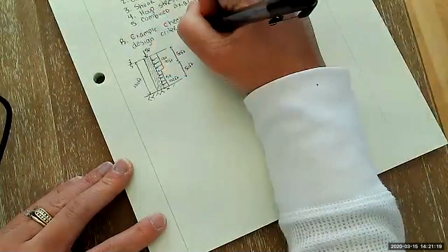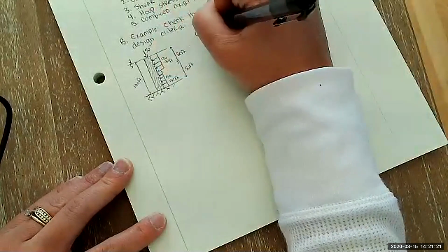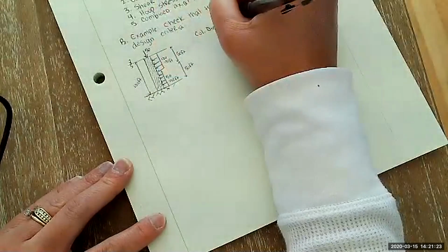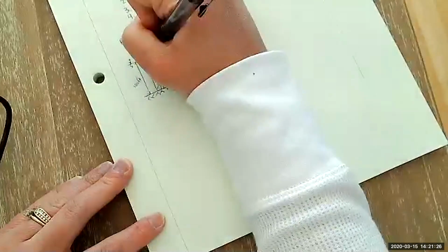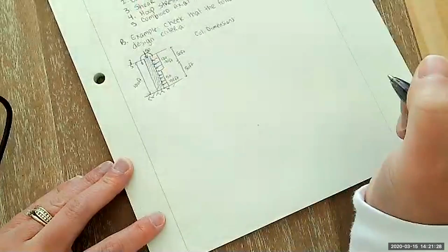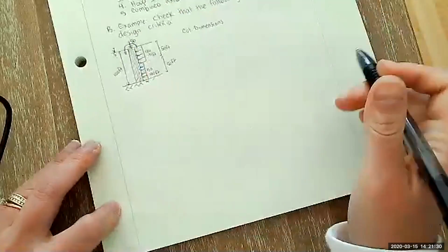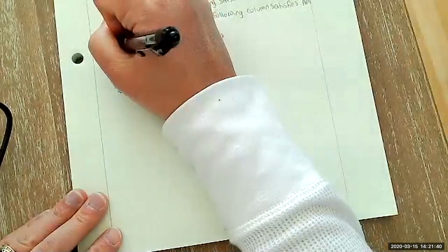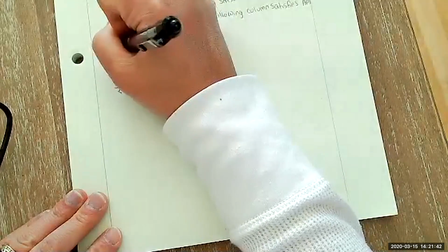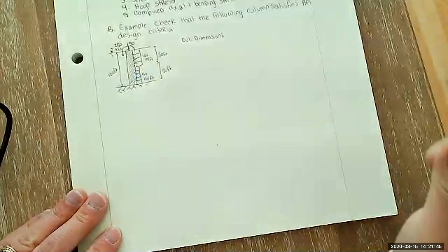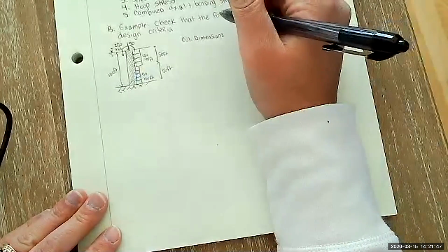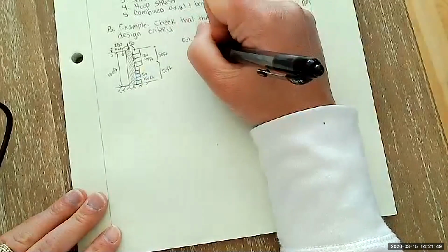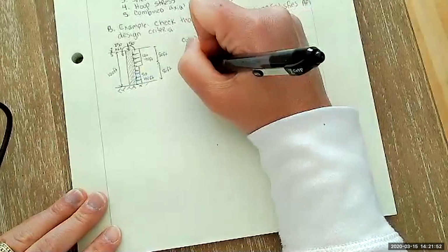And we're also given the column dimensions. Oh, and I'm sorry, I forgot one load too. We have a 250 kip foot load applied at the top of the column. Maybe that's due to the platform and where instruments are located or where the wind is blowing. So this is, again, 250 kip foot in the counterclockwise direction. Our column dimensions, it's a hollow column or a pipe.